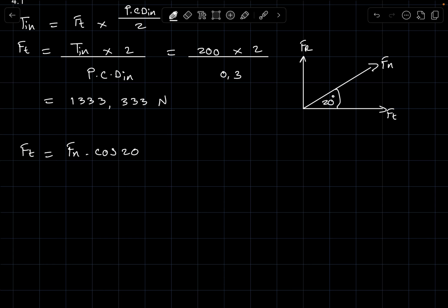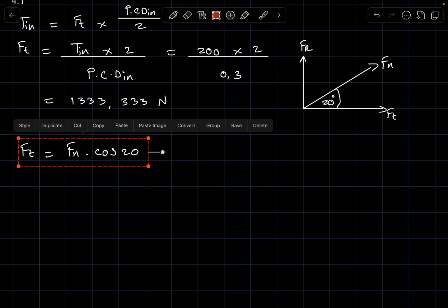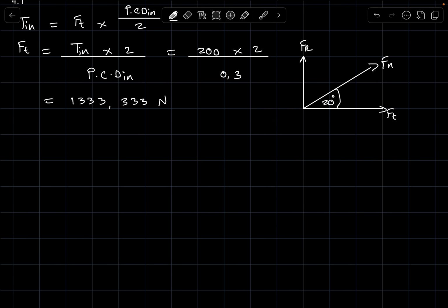So to calculate the normal force, Fn is equal to the tangential force divided by cos 20.